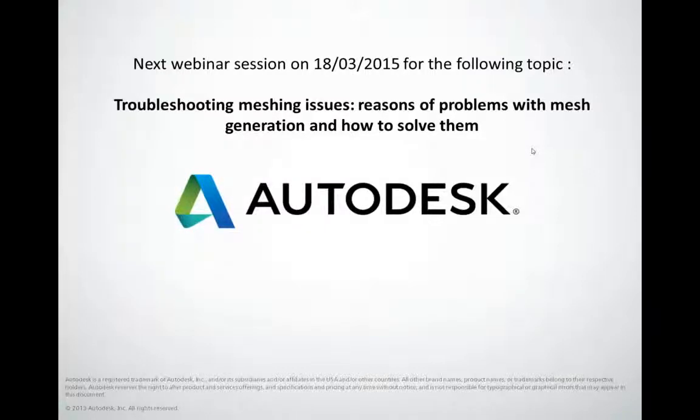Also, trying to answer this one about nodes along the edges. From experience, that's probably the use of the regular mesh for a model where you have either some nodes already defined at the edges or in the location of the edges, or there is some small inaccuracy in the definition of the panels. But as a first attempt, switch off regular mesh and use Delaunay mesh and see if that solves the situation. That would be the first option to try.